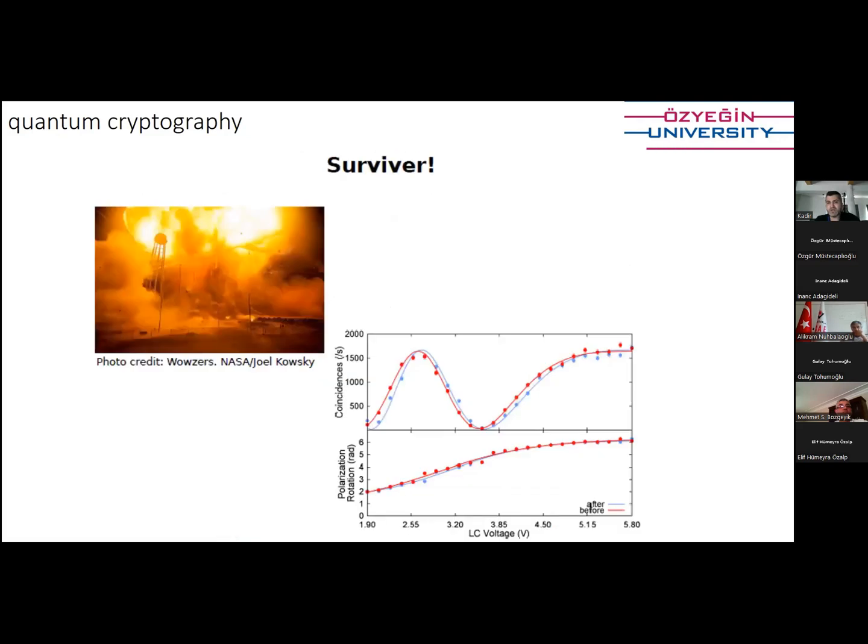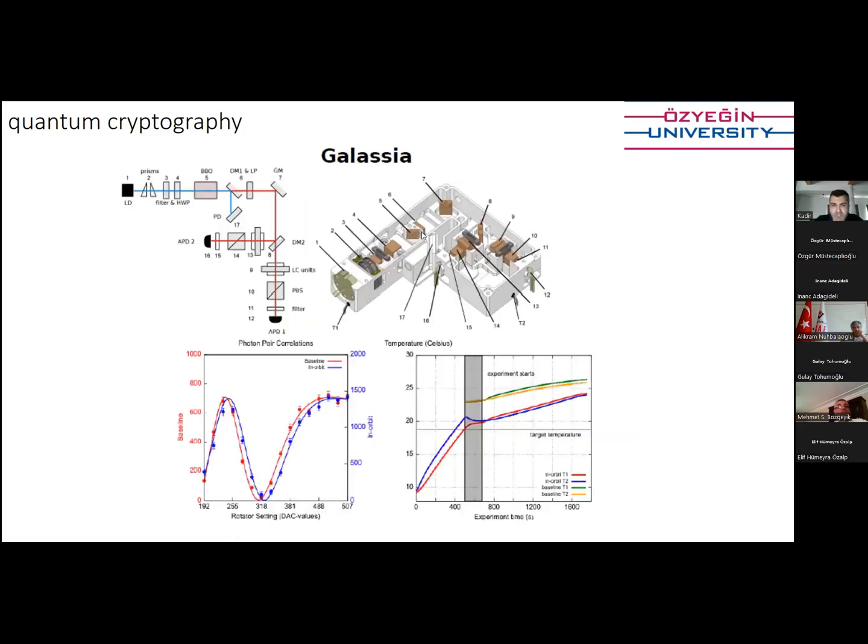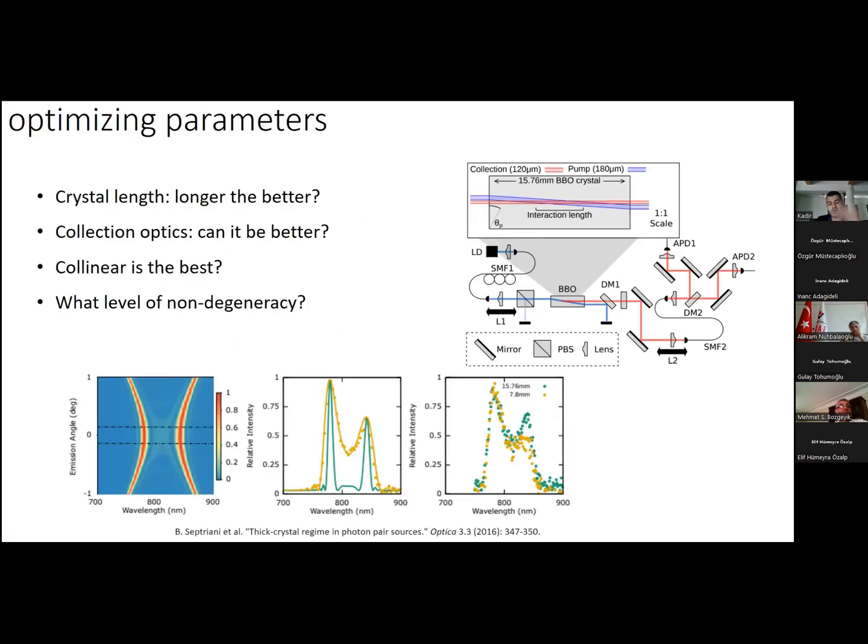So there are details of how you mount these things and all the stuff, but you see some titanium components here. The white color components are actually titanium components to mount everything nicely such that even with huge vibrations, even above 50 G vibrations, a rocket explosion, it's like a bomb, still, the dimensions do not change. So that was really good engineering actually, and a good indicator that now the quantum experiments are ready to go outside the lab.